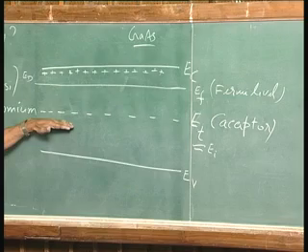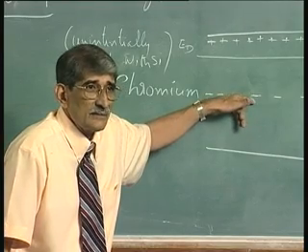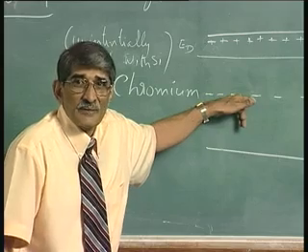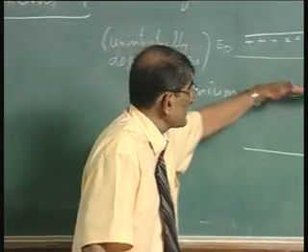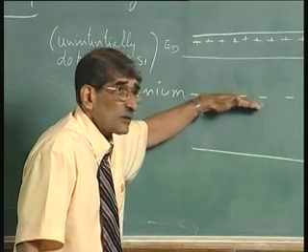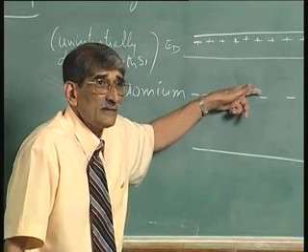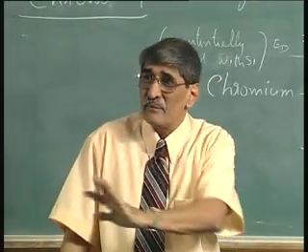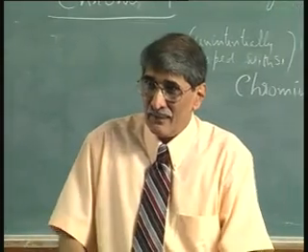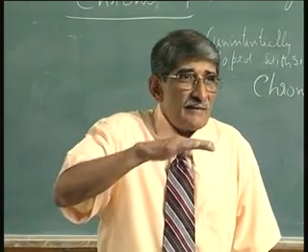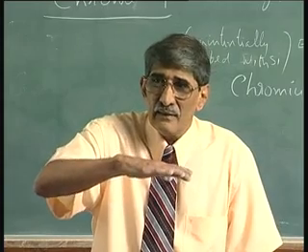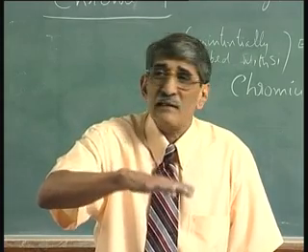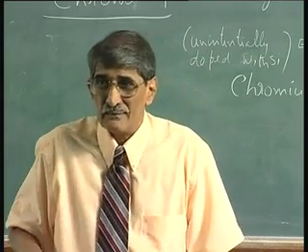Now, you can catch, if the Fermi level comes below that, what is the ionized state of this? It is not occupied. So, the Fermi level will actually go down. It cannot go down because then it becomes unionized. If it is not ionized, it is not becoming more p type. So, now you see, dynamically, when you keep on adding and it reaches a certain level, the Fermi level will get stuck at the middle, it will not go below that.